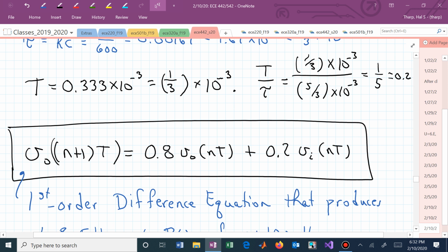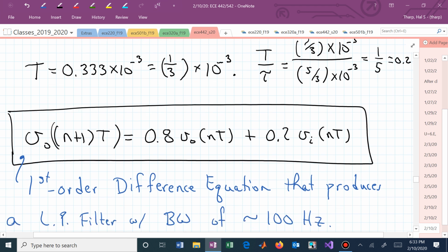It's a first order state space representation, and our system matrix, capital A, is 0.8. What's the eigenvalue of that capital A matrix? Capital A is 0.8. What's the eigenvalue of that matrix? 0.8. It's less than 1. It's stable. We would have expected that because we had a stable low-pass filter. Hopefully this discrete equivalent preserves stability. Some do not, but this one did for this simple case.